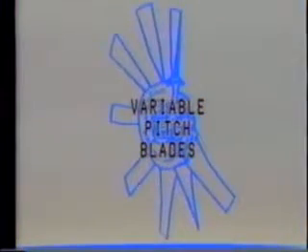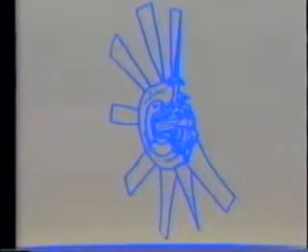A third option for controlling fan discharge is variable pitch blades. Variable pitch axial flow fans deliver an amount of air in accordance with the pitch of the fan blades. As more or less air is needed in the system, an actuator positions the pitch of the fan blades accordingly. The positioning of the blades is similar to the positioning of the inlet vanes. However, the fan is always spinning. Inlet vanes remain stationary. The degree to which the blades are pitched determines how much air can be gripped and passed on into the system.